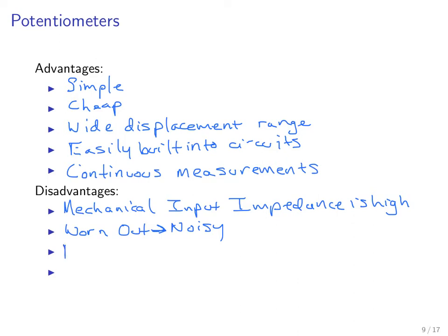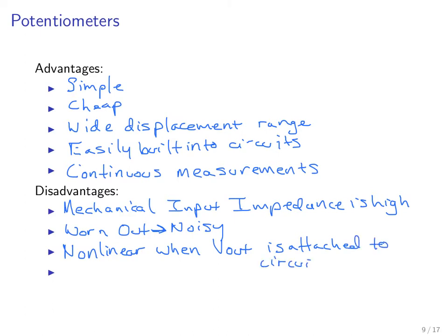They can be nonlinear when they are loaded with subsequent circuitry. That is, when Vout is attached to something with sub-infinite input impedance. So when it's attached to a circuit with a low Zin.